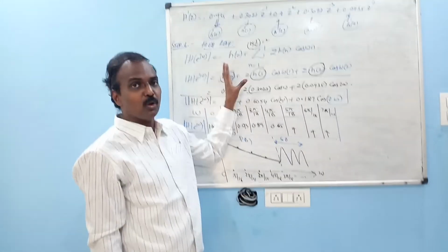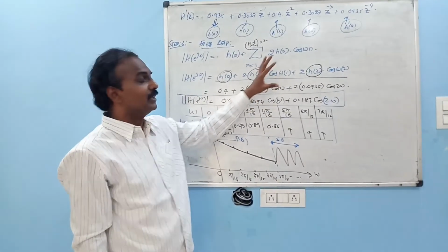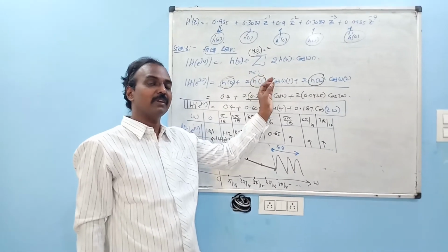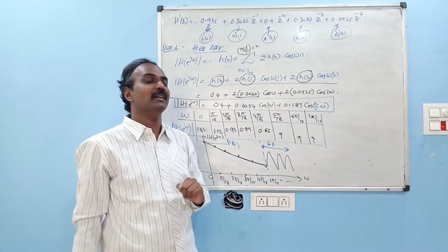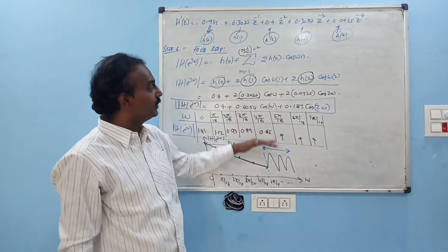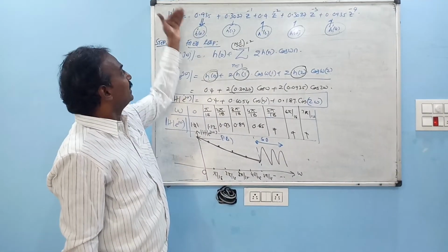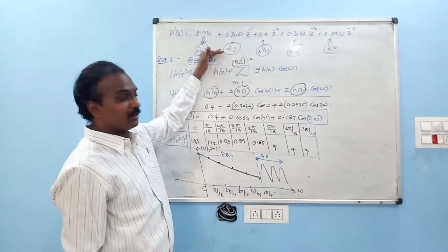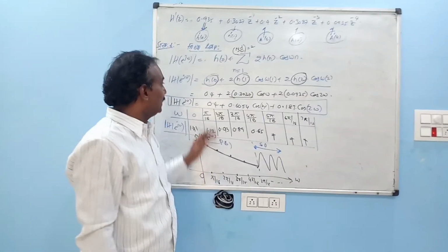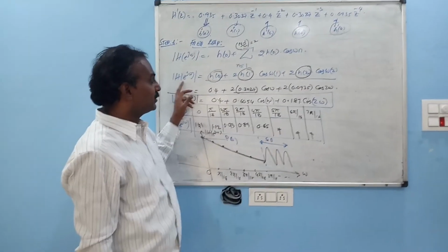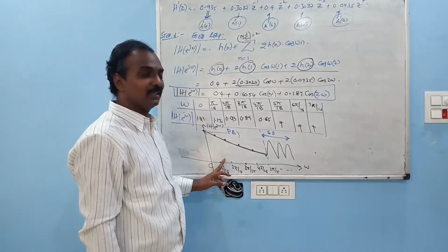This is designing a low pass FIR filter for 5 stages. So he has given the cutoff frequency FC as 200 Hertz and sampling time as 1 millisecond, right? From that we have designed a low pass filter, and we have seen the original coefficients, and after shifting by 2 units to make it causal, what are the new filter coefficients, then what is the frequency response we have seen, and we are trying to plot the graph of this frequency response.